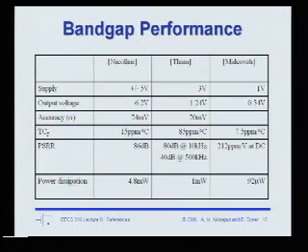Another thing that we didn't talk about today, but something to look out for, is if you are comparing different band gaps in the power supply, power dissipation, what other factors should you take into account that's not on this chart here? The noise? Yeah, noise. Definitely look at the noise that the band gap generates. And actually, you might say band gaps are great, why not use them everywhere? Well, they tend to be fairly noisy, so you have to weigh that against other considerations when you design circuits.